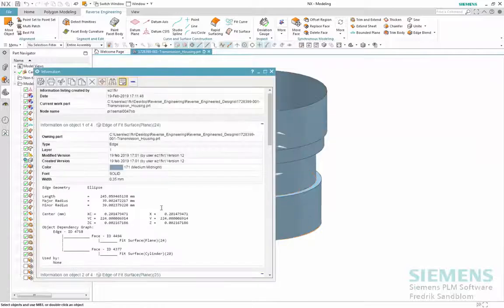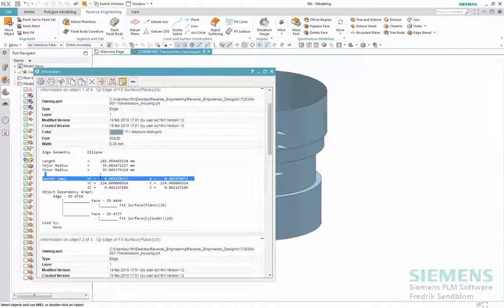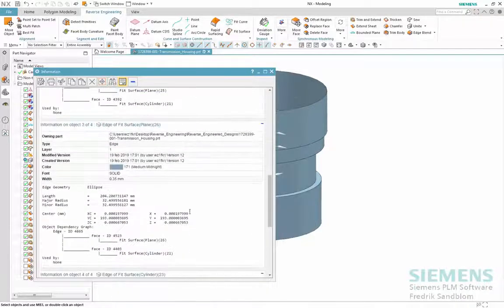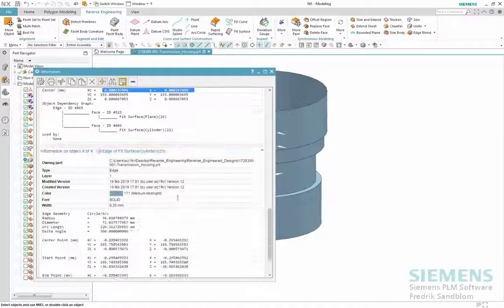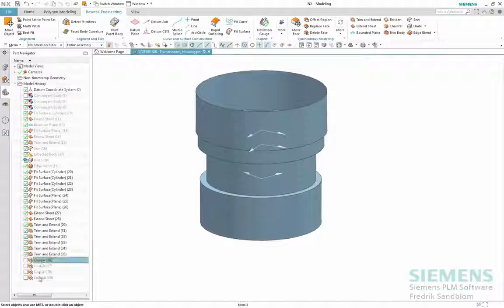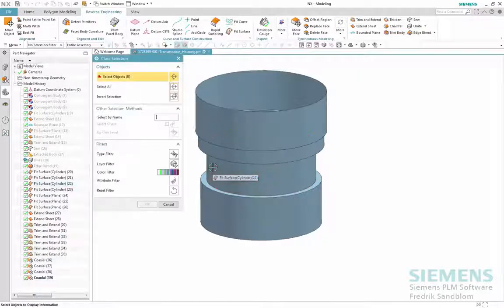We can see that it is slightly off, and we are now 100% sure that with the coaxial requirement active, all the cylindrical surfaces are coaxial to the reference axle, and we will obtain an optimal interaxle and gear relationship. Maybe even better than the original, as this failed alignment could be the reason for the damage in the first place.